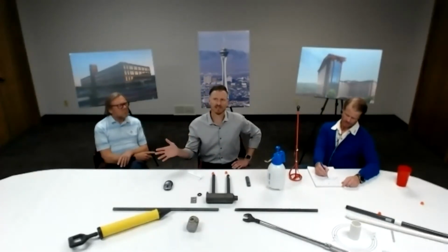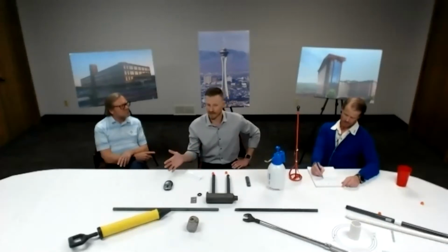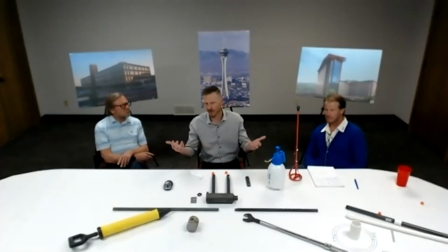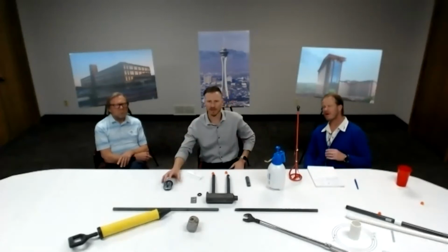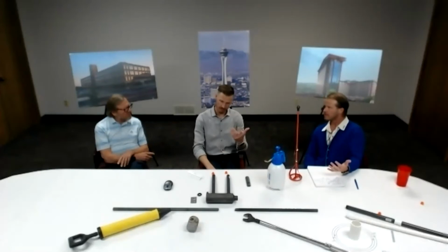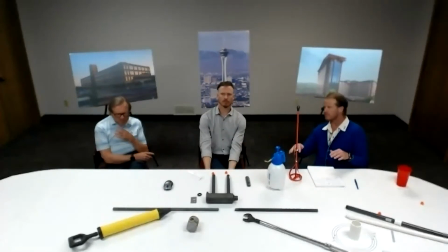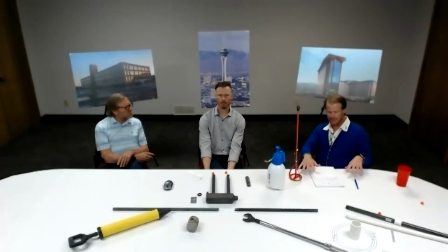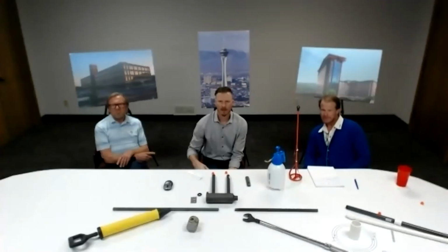A lot of architects these days are wanting exposed floor finishes, so we would have to work with how that might look if it's a finished concrete look that you're going for. Most structures get floor coverings, whether it's carpet, tile, or something like that. You're going to have one joint instead of two, and you will have a more continuous looking slab than having a 4-foot, 8-foot gap where your typical pour strip may be discontinuous in color.